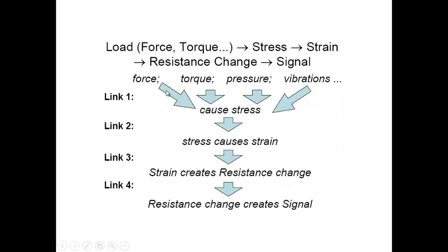Okay, this is what I'm telling you. From load we get to the stress, but you can't measure the stress, so you go for the strain. The strain will cause a resistance change, and from that we can get the signal. Okay, this is how the process works. You have your load, which causes a stress, and stress is because of strain, and the strain will create the resistance change, and from the resistance change they create a signal.